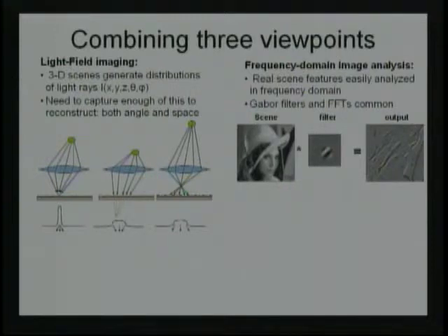So for example, here what you see is the standard reference image processing people use. You convolve it with a particular filter that has this impulse response, and you get back, in this case, a representation of only the diagonal edges in the scene. The reason this is considered a good idea is that most of this new image is the same gray zero color. And so you can compress it a lot because it's a very sparse representation. Most of the results are zero rather than something more complicated.